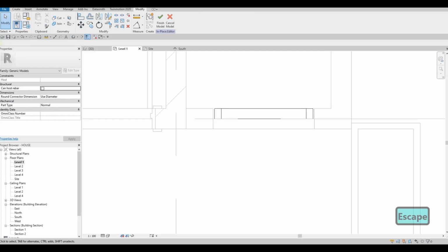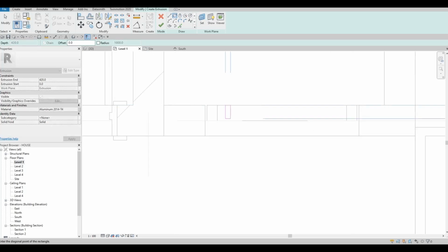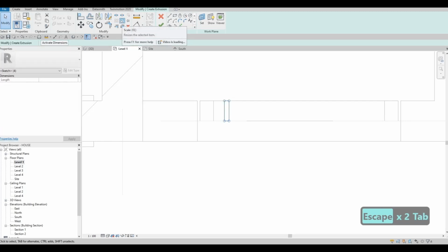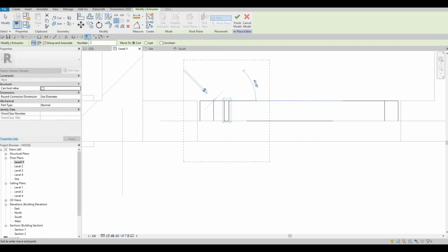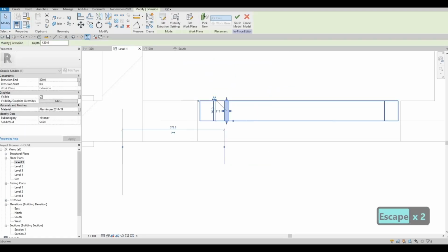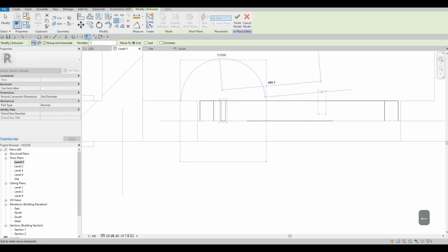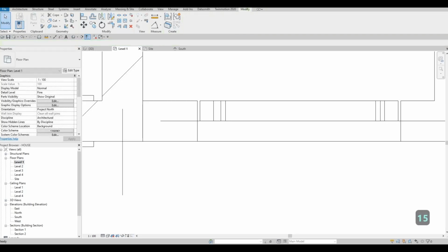half of that, and then create again, extrusion, set, pick a plane, and select this one over here, and we're just going to add something like that, and then we could create, so we have this one, click finish, same thing, and then now what we could do is array this, so from here to, sorry, let's do this properly, so array this from here to the last, maybe I want 15, then click finish.